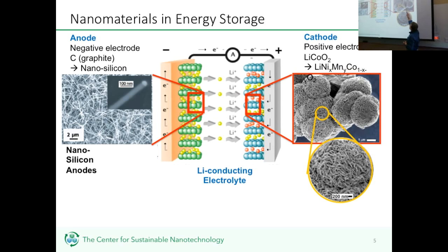But the bottom line is that's driving a tendency to look at other kinds of materials that replace cobalt with nickel and manganese. So this leads to a class of materials called NMCs, nickel, manganese, cobalt. So the recent Nissan Leafs and a lot of the other electric vehicles now are moving away from other metals and going toward these nickel, manganese, cobalt. And if you're lucky enough to have a Tesla, that is a nickel, cobalt, aluminum alloy that's used in the cathodes there. Okay, so there's a lot of activity in the energy storage area in terms of new materials.